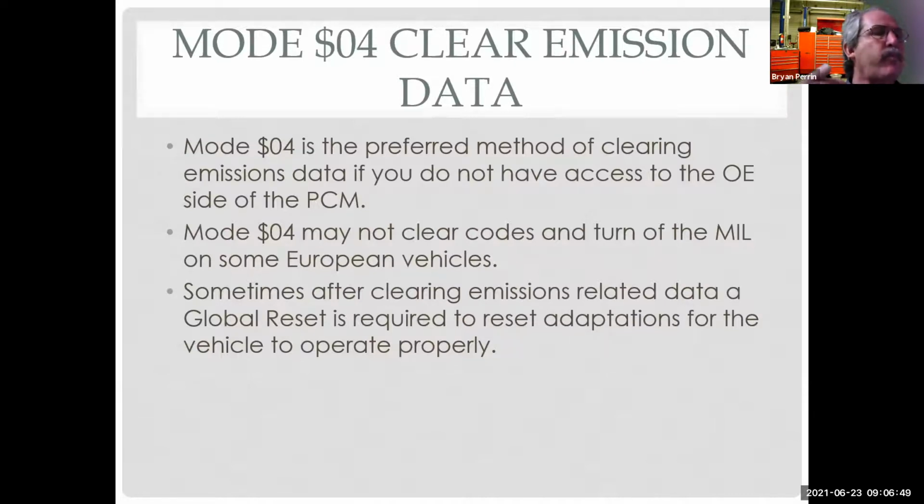So the only way to do this was to have an enhanced scan tool where I could go in and talk to the diagnostic module, clear the diagnostic module code first, then clear the engine control module. And I had to do it all through the enhanced side. And I made a fair amount of money doing this because a lot of shops that were trying to work on Mercedes didn't have a European scan tool. So they'd kind of fix the car, do everything else. They'd come over and I'd get paid to reset the system because they didn't understand what was going on. And I had the tools, so I wasn't telling them. I was just taking their money.